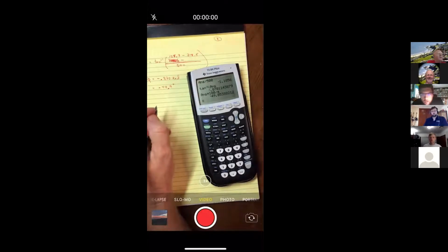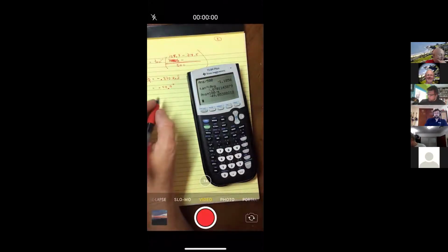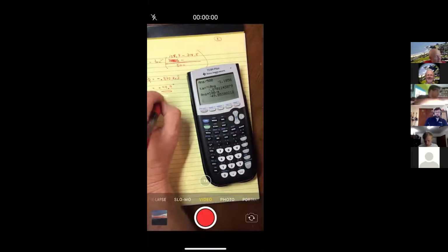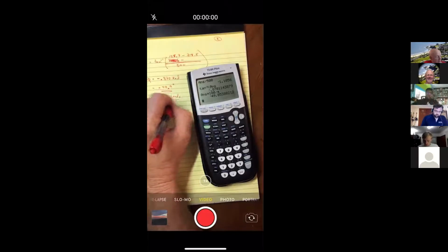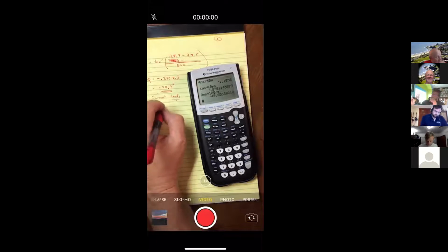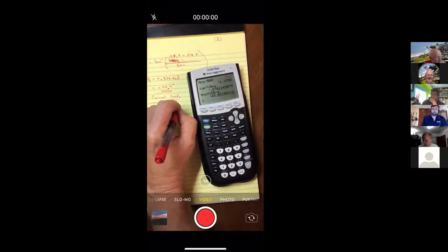So that's ultimately what this question was about, I think. It said, determine the phase angle. Okay, so I did. The phase angle is negative 49.9 degrees, by which the current leads or lags the voltage. And so the current leads. Or to put it another way, the voltage, because that's really what we've solved for in this equation. We solved for voltage. The voltage is a negative number, so the voltage lags.